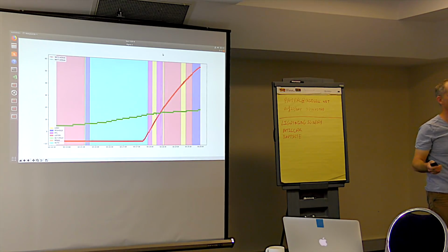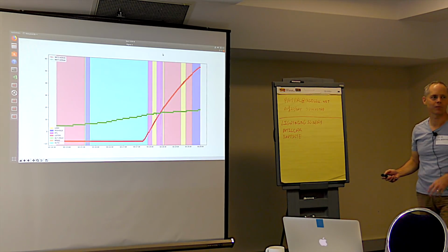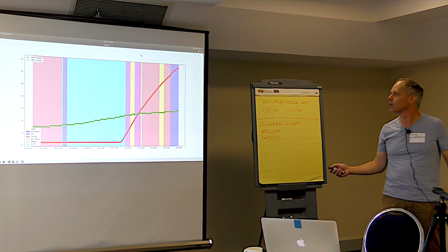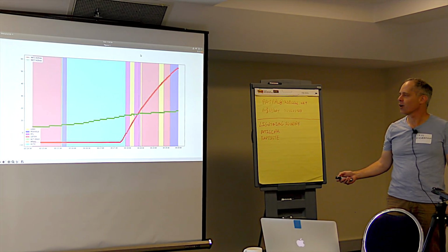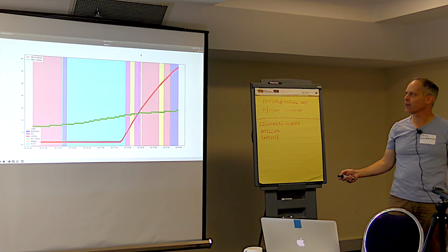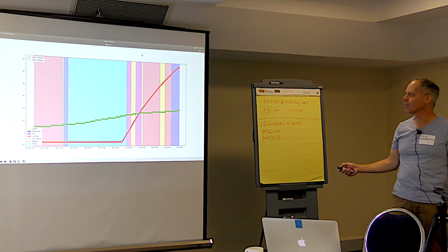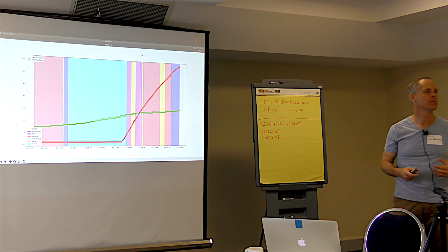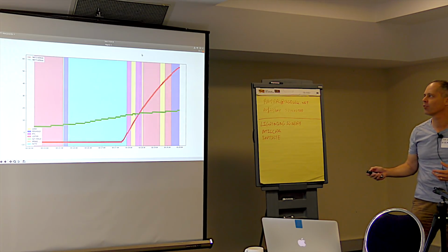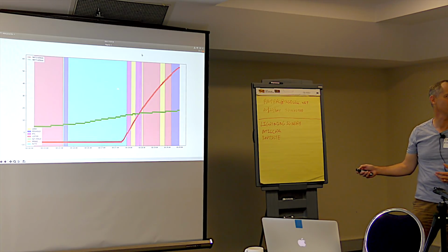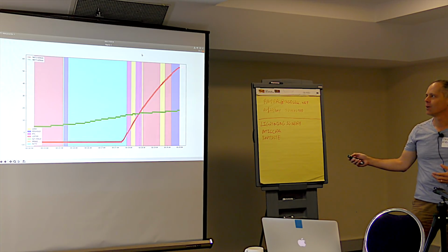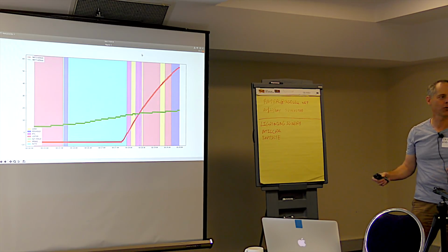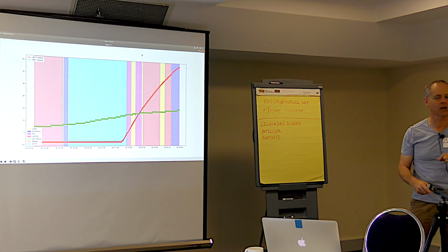So they're trying to economise on use of log data and it's logged as an integer. So here's the second IMU, and it's slowly adjusting throughout the flight, which is typical for something that's warming up. You see these sort of drifts in bias values, but you get this sudden ramp up in bias. The EKF is trying to learn and compensate for an offset in the Z accelerometer.